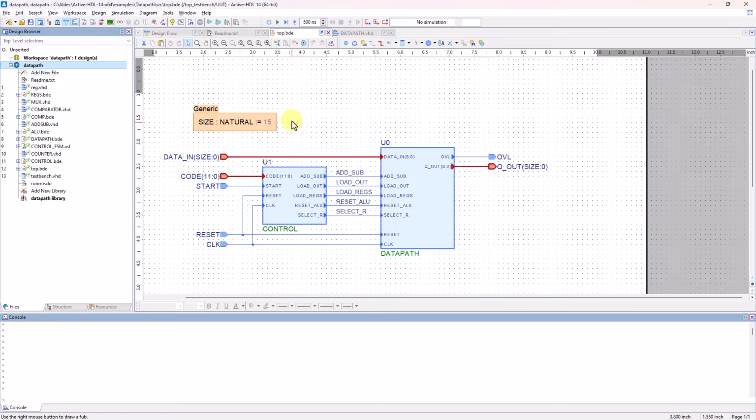And this is handy because if you're doing a batch of simulations in one sitting, you won't be able to access debugging while it's doing that. But with post-simulation debug mode, you can pull the database file each simulation creates and analyze what happened after they've finished simulating. And because this mode doesn't require Active-HDL to use the simulation kernel, you can share the simulation data with other members working on the same project for them to analyze as well.